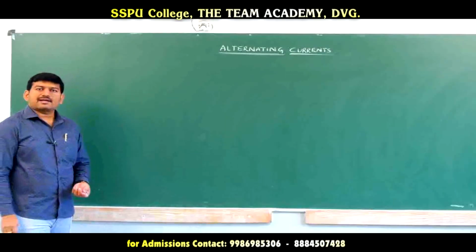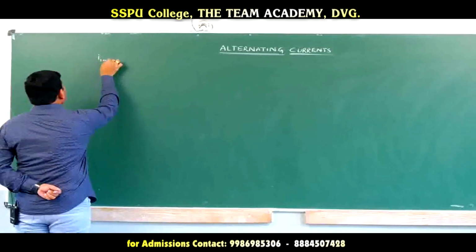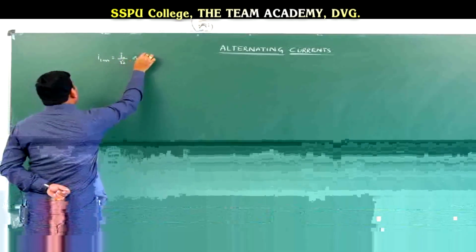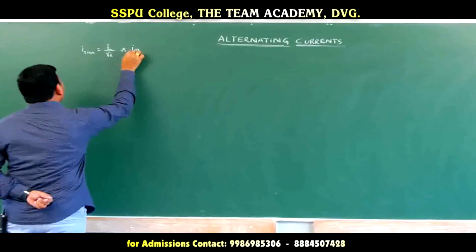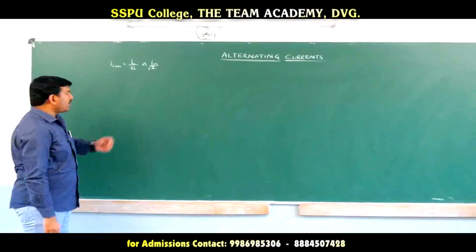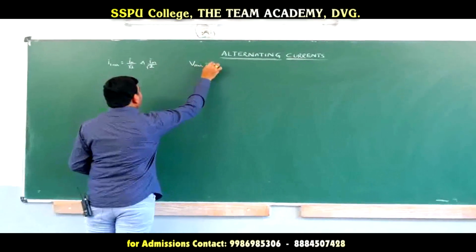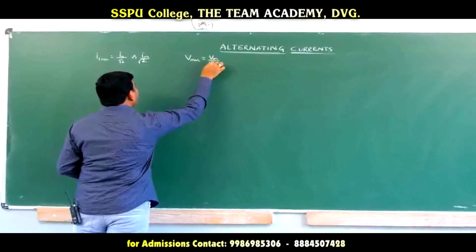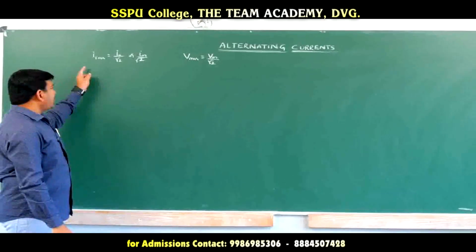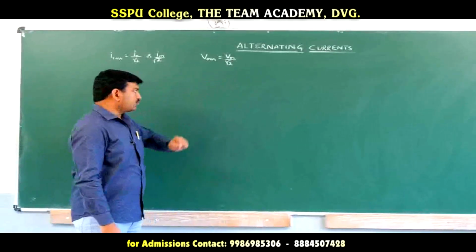We have calculated the RMS current value and we got I RMS equal to I naught divided by root 2, or I maximum value divided by root 2. Yes or no? In a similar way, if this is true for currents, then for voltages I can write V RMS, the RMS voltage, equal to Vm divided by root 2, where Vm refers to the maximum voltage. So I RMS is equal to Im by root 2 and V RMS is equal to Vm by root 2.